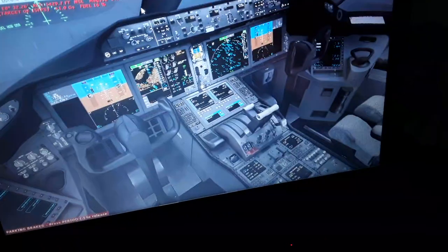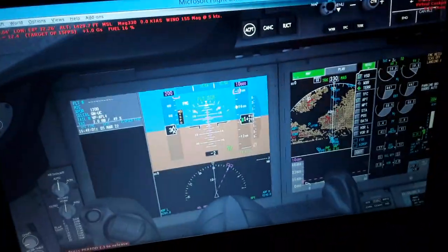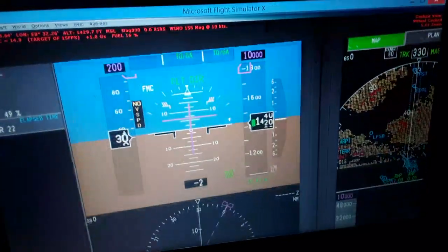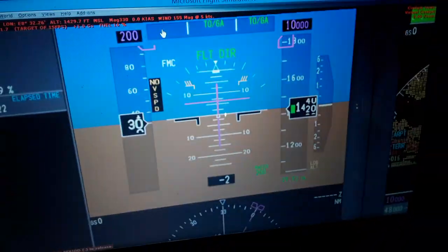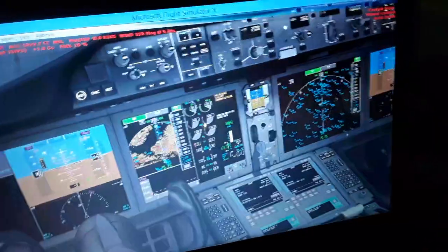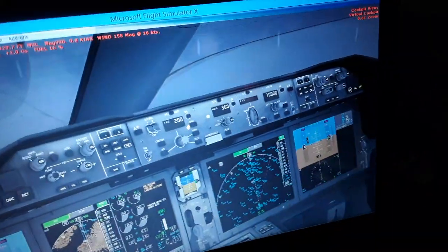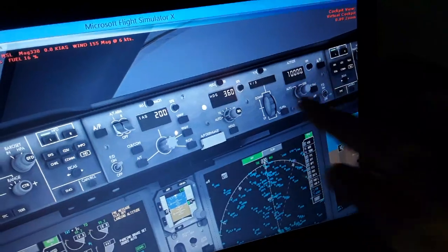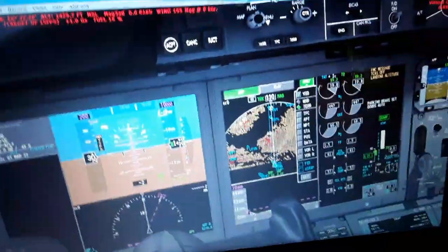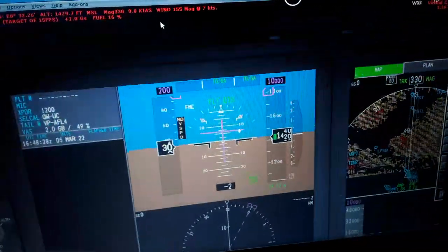So we have here, you can see in the primary flight display, the airspeed indicated, the airspeed tape over here. You can see the airspeed selected from the autopilot flight director system panel. It's the same 200 knots. Also the airspeed guidance here, the heading guidance, and the altitude guidance. The altitude selected from the autopilot flight director system panel. So you can see here also in the primary flight display and the HSI.